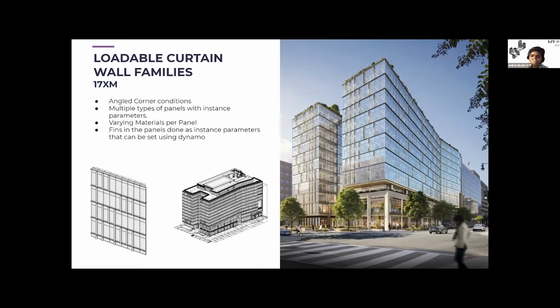There's also a fin situation happening all over the facade, where the design was changing at a pace that it was difficult to replicate inside of Revit. So there was a Dynamo solution that was available for the team. And this is early Rhino.Inside, when Rhino.Inside was not very stable, which allowed the team to not manually place the fins on the curtain walls, which we're going to also do in the workshop later today, just to see how we can automate that.